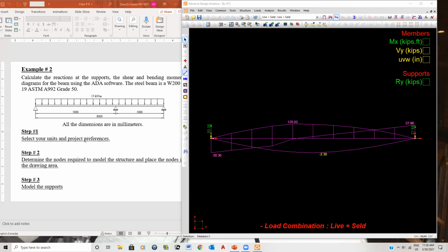Now what we're going to do is model this one. Fair enough. And I think we did this one in class, and I want to show you, of course, we did this by superposition, where we removed this, calculated the deflection, calculated what the force would be to bring that deflection back up to 0, calculated the reaction here, and then we were able to calculate the reactions there.